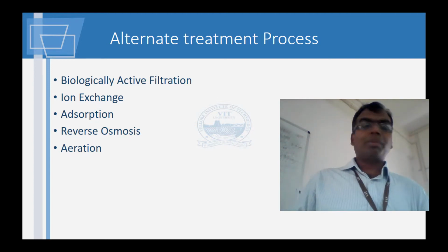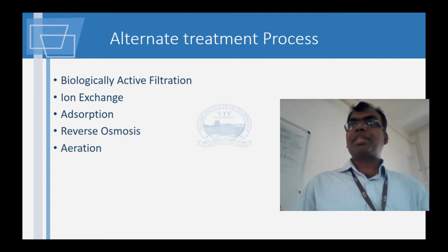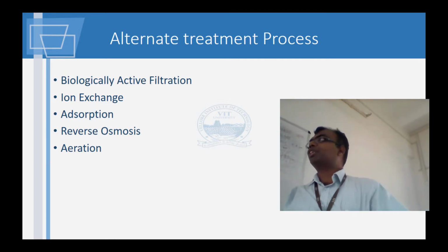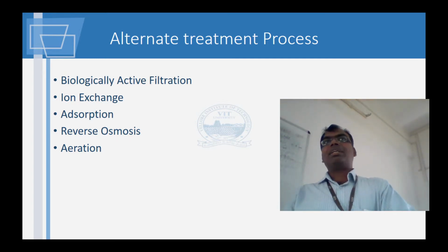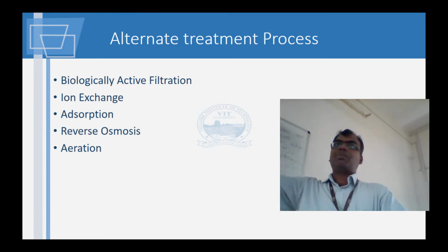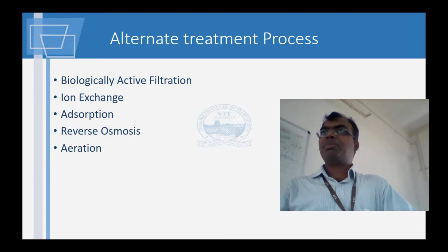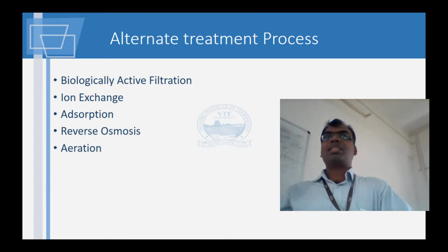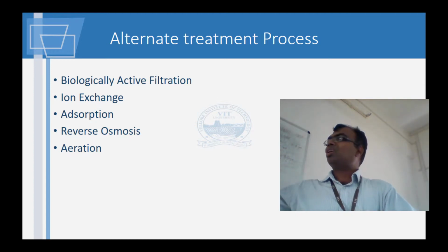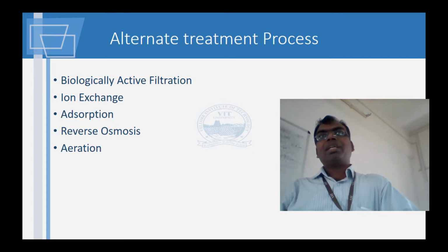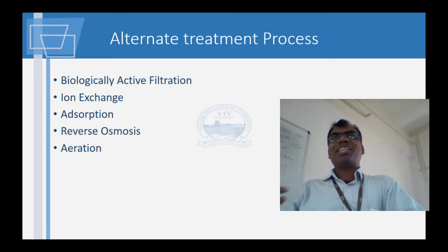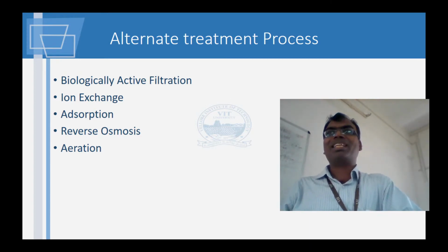Then adsorption, we spoke about adsorption in activated carbon. Okay, it can be in powder form or it can be in granular form. And if you have an Aquaguard in your house, inside they'll have one candle of activated carbon. It removes all objectionable taste, and things like hydrogen sulfide which causes odor, all that can get adsorbed on the surface of your activated charcoal. In fact, do you have an Aquaguard at home or something like that, RO?